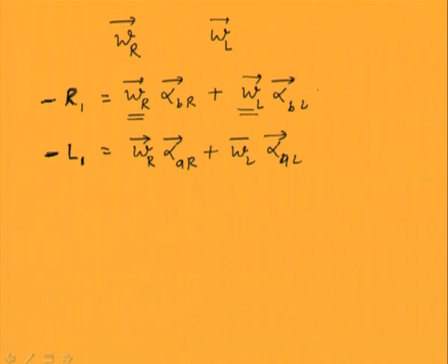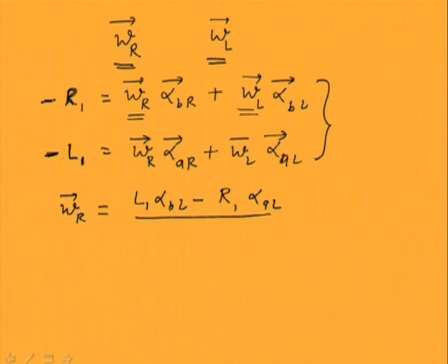Now you can see that this can be solved for these two correction masses, and the expression for that will be, and the denominator contains the influence coefficients. The advantage of this particular vector quantity is that we can write them in a complex form.